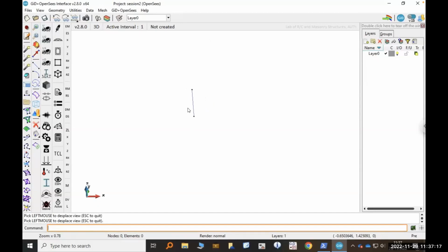Now, if you recall earlier, in OpenSees you build nodes and elements, not here. In this program, you work with it just like any graphical user interface. So you're building a geometric object, a beam, a column, a geometry that you can later mesh. And this is another reason why I don't really think OpenSees needs a mesher, because meshers are freely available. There are so many open source meshers that you can use. And just like here, our graphical user interface already has a mesher.